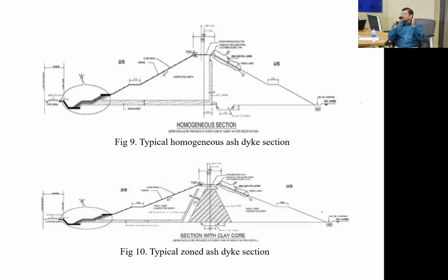You are creating a zone where between the liner and the soil, there is a gap. All the water will go there. So the objective is good, but you have to make sure that the liner stays tight, installed very far into the ground.